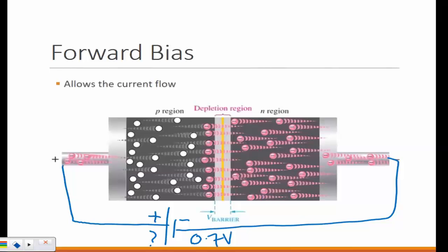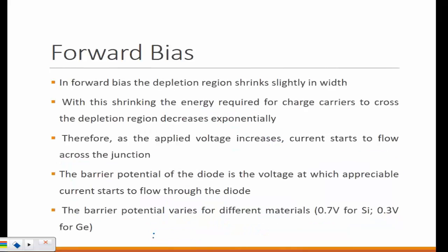You will see some curves that show the diode behavior. There you will see in a little more detail what the shape of the curve is. But always remember that whenever you are forward biasing, even if you have 0.4 volts here, a little bit of current will be there. But it's not enough to serve the purpose of the diode, right? But let's say, for example, you have enough voltage. So all the electrons will be pushed through, because remember this is the voltage source.